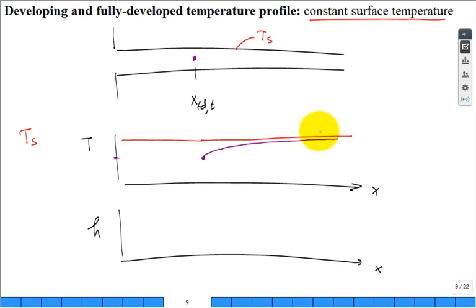What do you think the shape of that equation is? Exponential. That's right. I know that you have a new favorite called the hyperbolic tangent, and a new favorite known as the error function, but don't forget your other old favorite, the exponential shape. As you go down, further and further, Tm is going to get closer and closer to Ts. It can't get any higher than Ts.